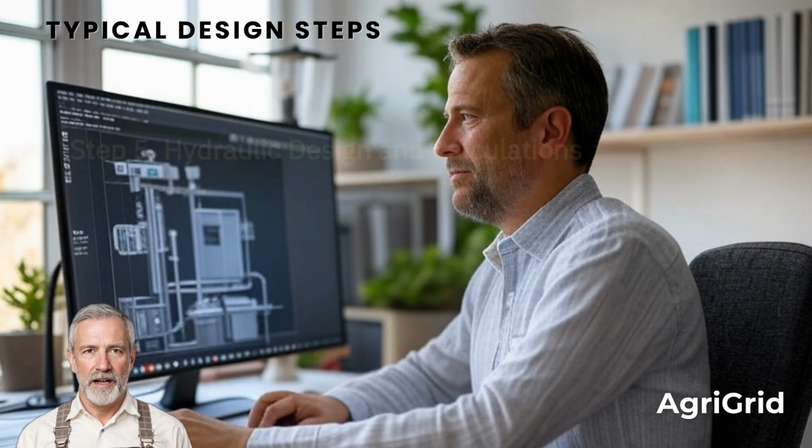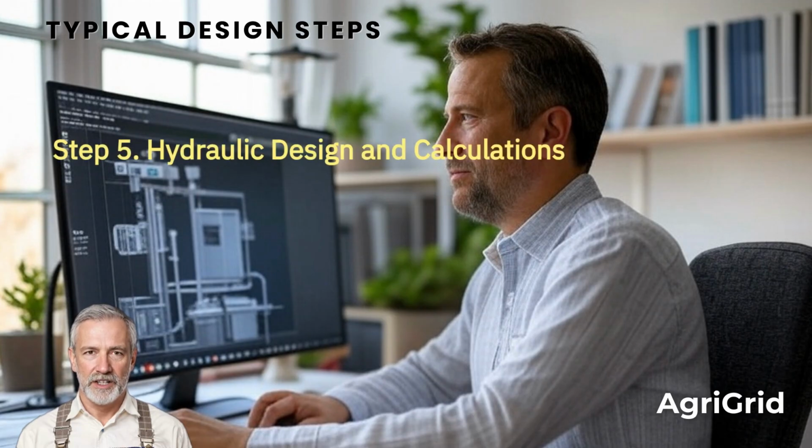Step 5. Hydraulic design and calculations. This is done to ensure the system delivers water effectively. You will calculate water flow rates and pressure requirements for each zone and determine pipe sizes to avoid pressure loss or over-pressurization. You will also account for elevation changes that affect water flow. During this step, you will also size the pump, if needed, to match the system's demand.